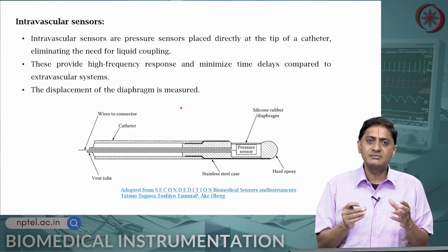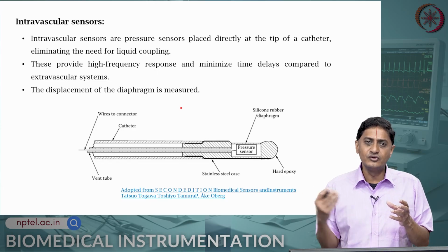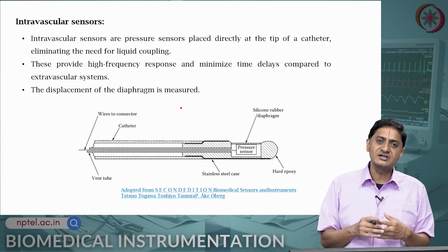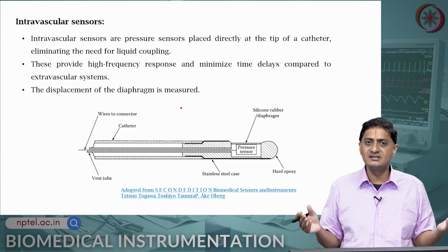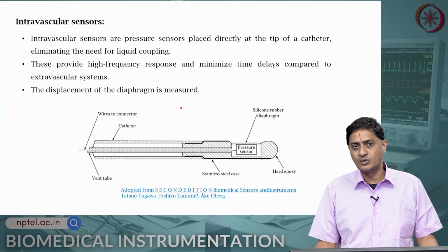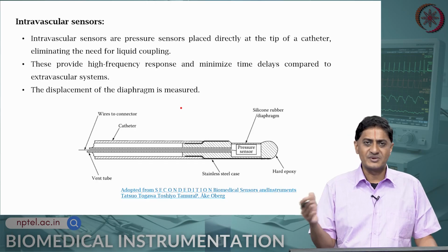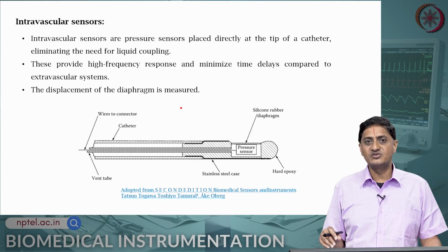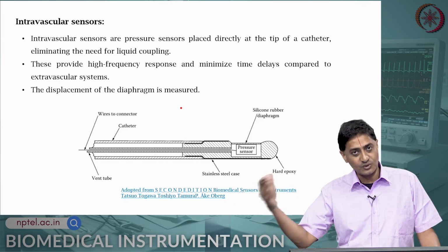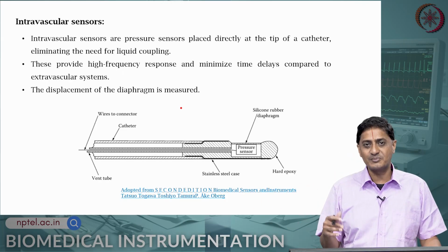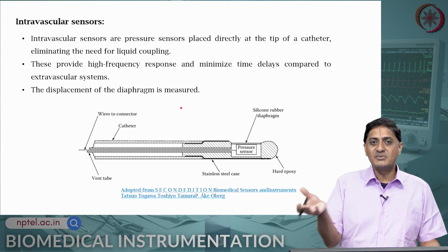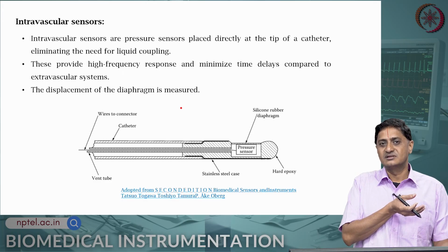There is a direct relationship between fluid flow and the deformation that you measure, and the deformation can be expressed in electrical terms that can be measured, for example as voltages. If it is capacitive, then the capacitance will change. If it is piezoresistive, then the resistance will change and the voltage will change. If the capacitance changes in the capacitive sensor, then that will also cause a voltage change, and I am measuring the voltage outside, for example.